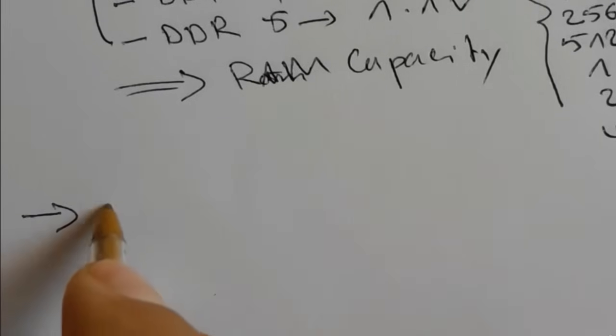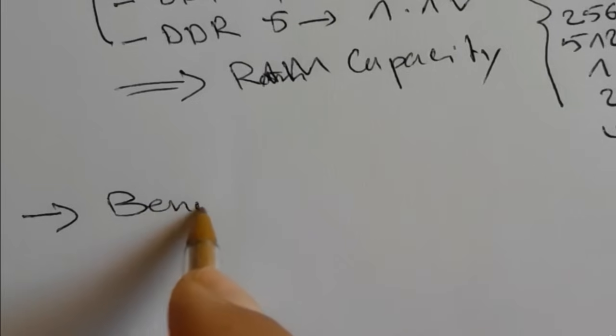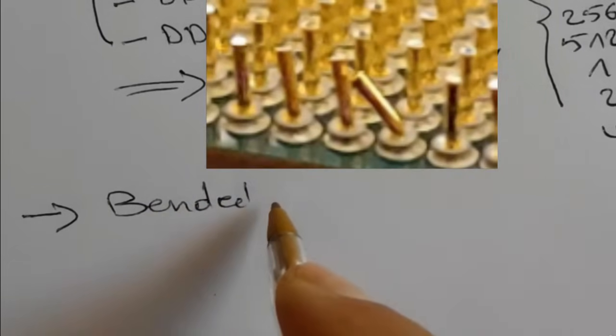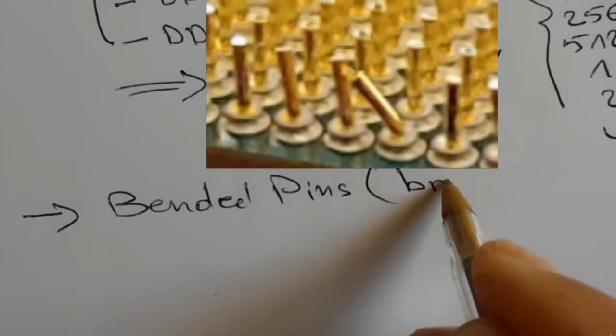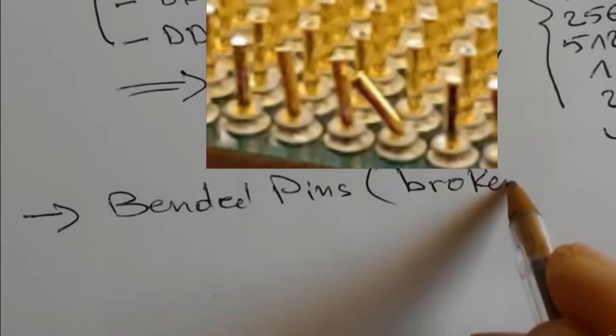So let's say right now the next fault that you can get usually in laptops, the bended pins. Okay, this is a very common fault.